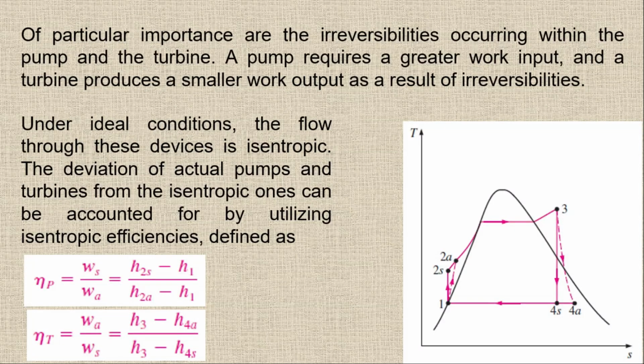Normally, cavitation occurs when the localized pressure is less than the saturation pressure. Then there will be formation of bubbles. Also, there is rapid vaporization and condensation of the fluid at the low pressure side of the pump impeller. All this basically creates issues, and it can damage the pump.